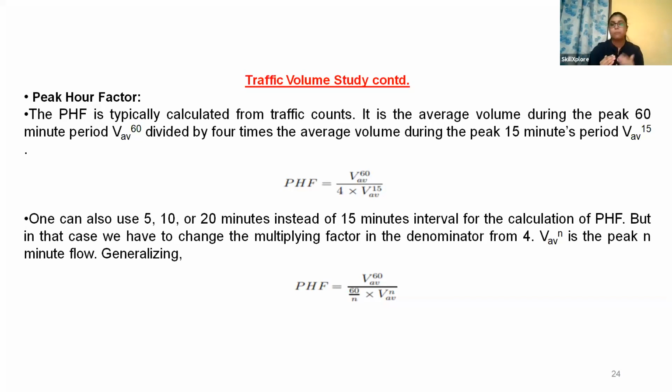So 60-minute traffic divided by 4 times the 15-minute maximum traffic is known as the peak factor. I have seen more than 4 or 5 times that they have asked peak factor questions alone in your examination. So that is one important thing.